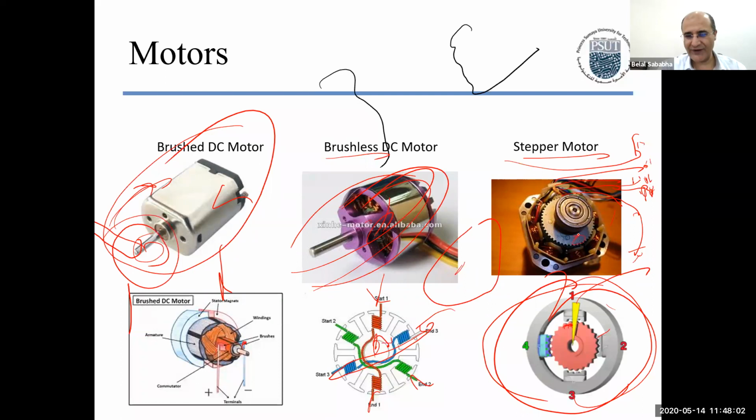But for this one, since you control the steps, I know, say, 100 times. If I put this in a loop, say 10, or 1000, and I know that I need 200 steps for this to rotate a full cycle, and I have 4 lines, so I need to do it 50 times, right? 50 times 4 equals 200, right?